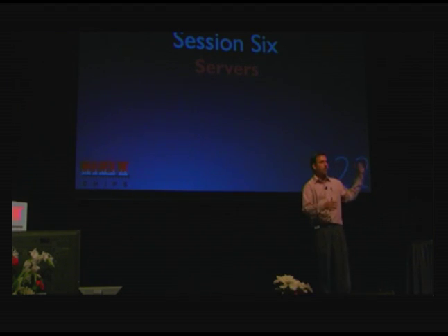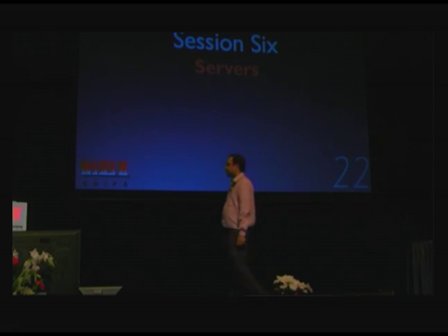If I understand your question right, you have one core in C6 on the socket, and maybe another core is active. Then you have an access from the other core, but that can never be cached in the core that's in C6 because the local cache in the core is flushed before you enter C6. Okay, thank you. Thank you very much.